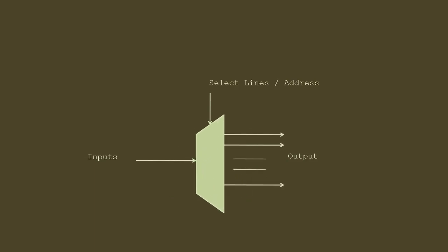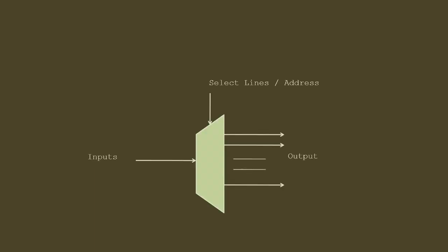The opposite component of a mux is called a demux. A demux works this way: based on the select line, if the select line is 0, we connect this input to this output and connect the rest of the outputs to 0. If the select line is 1, we connect it to the next output. If it's 2, we connect it to the next output, and so on. So this is called a demultiplexer, or demux for short. These are the more commonly used components. There are more to follow, but I'll do a small example here.